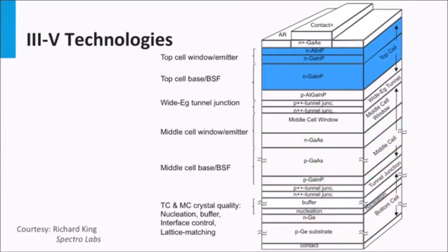The p-n junction at the window layer at which the solar light enters the PV device is called the top cell. As the spectral part with the most energetic photons like blue light has the smallest penetration depth in materials, the high bandgap junction always acts like the top cell.